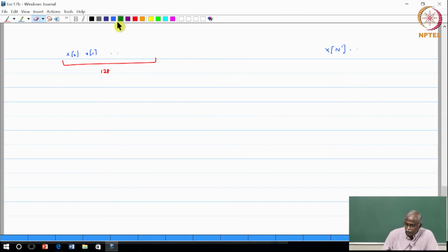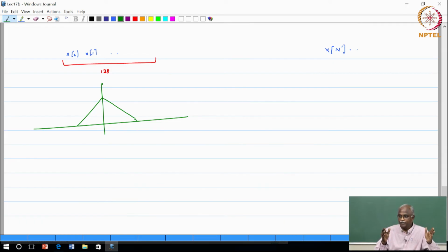So, if my input spectrum, the true spectrum, had this shape, the minute I multiply it with a rectangular window, I have modified my sequence. It is no longer this spectrum. So, actually what is the spectrum? It is this convolved with a rectangular window. Spectrum of a rectangular window is a sinc function. Okay. So, already I have modified it. So, you have to go back and revisit what I am calling the delta function, because it is actually how we interpret the process.